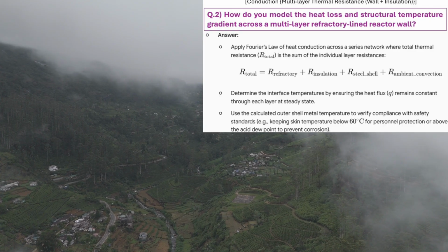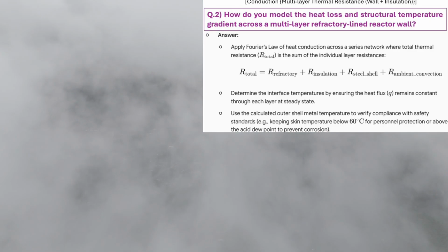To protect the steel. Exactly. The objective is to keep the thick, low-alloy steel pressure shell operating safely within a narrow design window, usually 200 to 250 degrees Celsius. And what are the two opposing limits we have to check?